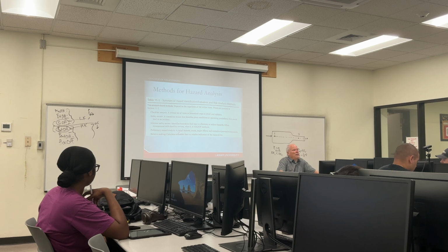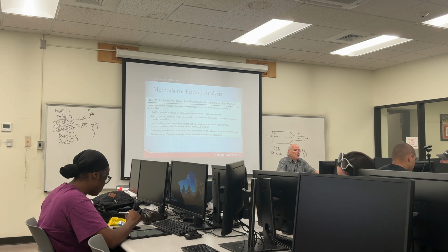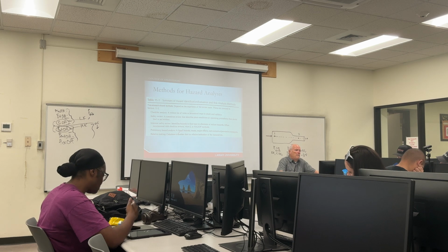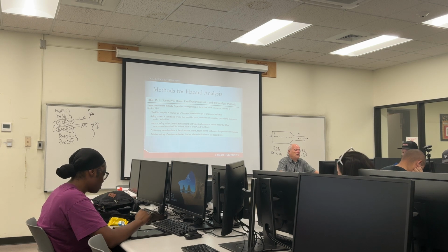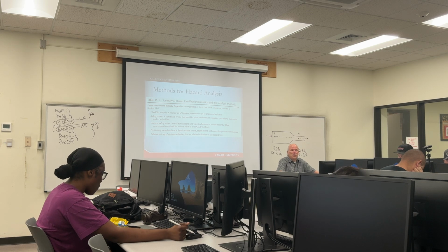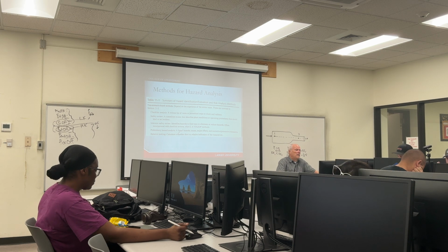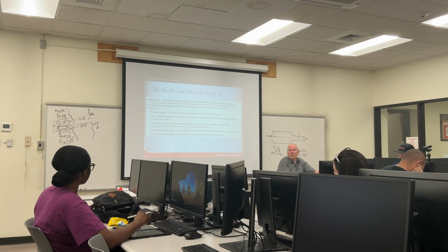So you've got non-scenario based methods. There's a checklist analysis you do. You do a safety review, you do an inherent safety review. Sometimes that's included in some other methods. You can do a preliminary hazard analysis. And preliminary is kind of where you're at with your project. And you do a relative ranking. So that's non-scenario based methods. You should incorporate that as part of your project.